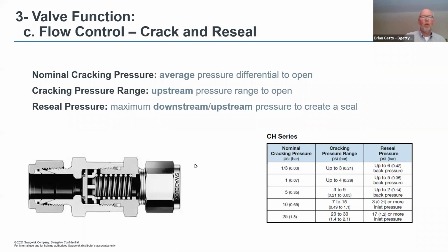Something we get quite often: customers will call up and say, "I want my nominal cracking pressure, but it doesn't open at that pressure. Why?" And then the reseal pressure. So we've got a chart here. If you've selected a valve that's got a 1/3 psi cracking pressure, it's not going to always open at 1/3 psi. It could take up to 3 psi to get it to open.